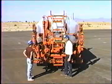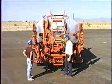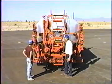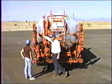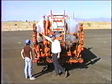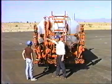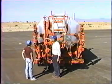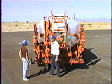If you've got one plugged up hard, the very best way to clean it out is with live steam. That is, go back to somewhere that has a good hot steam cleaner, something that'll make good live steam. Any tank farm has live steam that they use to heat the tanks with. If you have live steam available, you just screw it into the end nozzle in the spray bar and let it leak there a little bit, turn the steam on. Steam carries a terrific amount of heat. It's one of the best heat transfer media there is. If it's leaking out there a little bit, that area will heat up fast.